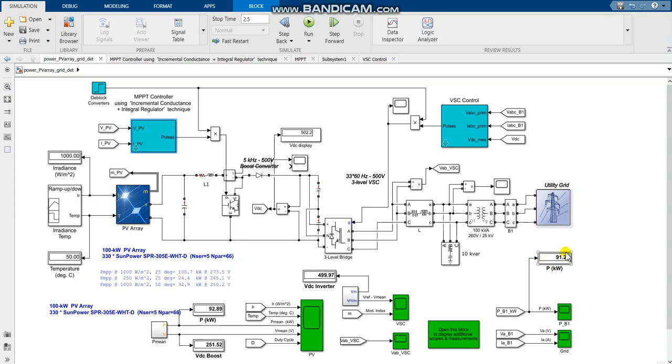Now, this high efficiency percentage just stresses the need further for having MPPT controllers for larger solar array systems. This allows the system to constantly be operating at or near the maximum power point. Without such a controller, you would be unable to control the power point that the system was operating at, and thus a lot of the power coming from the PV array would be lost, the efficiency would decrease, and the output power would be a lot less.